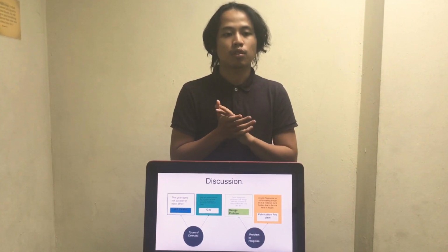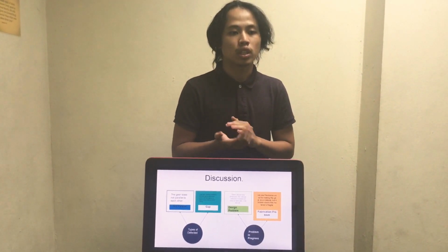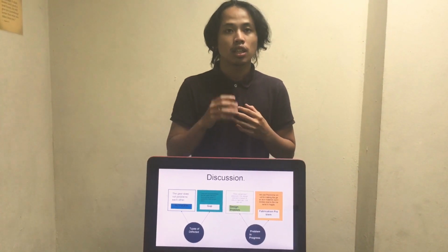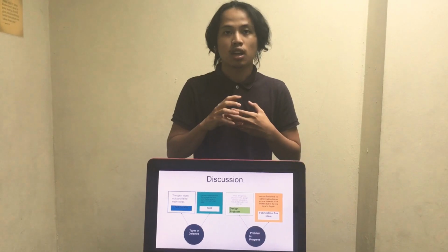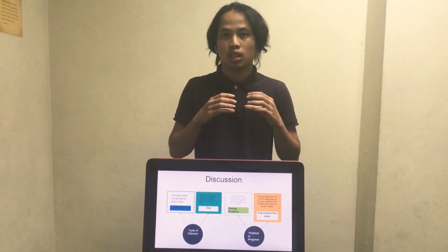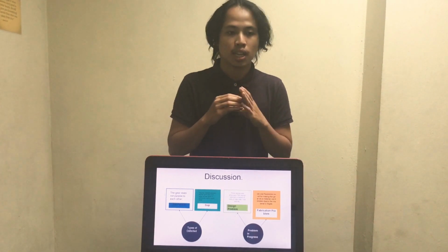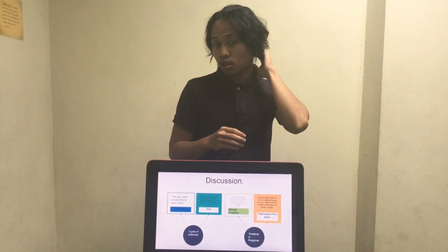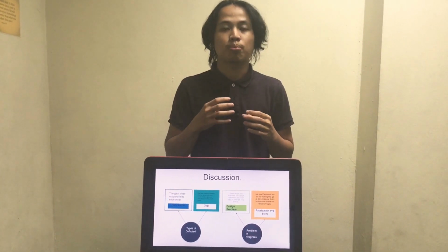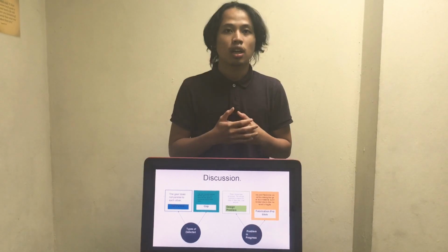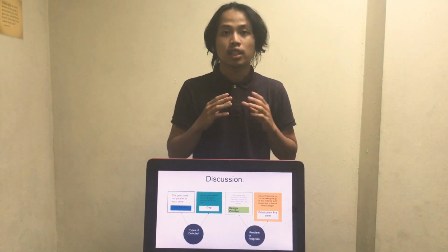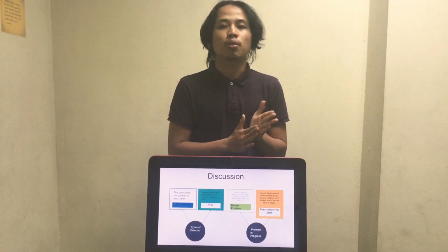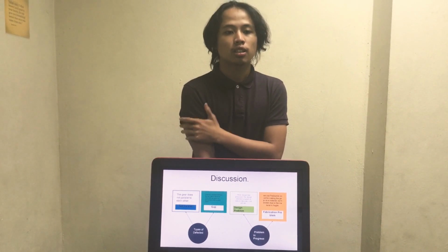And the second type of defect is the gap. A gap is needed between the two gears because when the two gears are placed too near to each other, the gears are very hard to move because they need some angle to move. The fabrication of the gear is quite poor because we are only using hand tools, and the gear is not quite symmetrical.